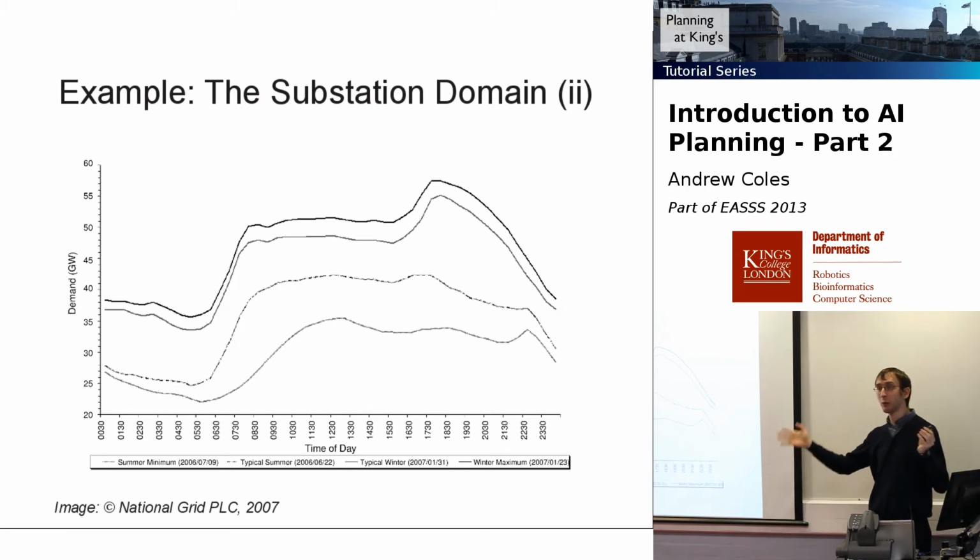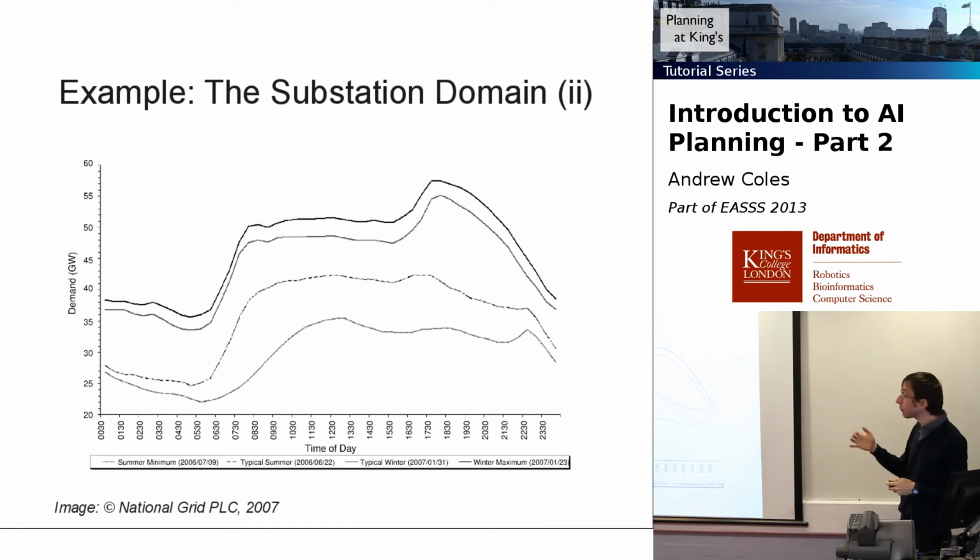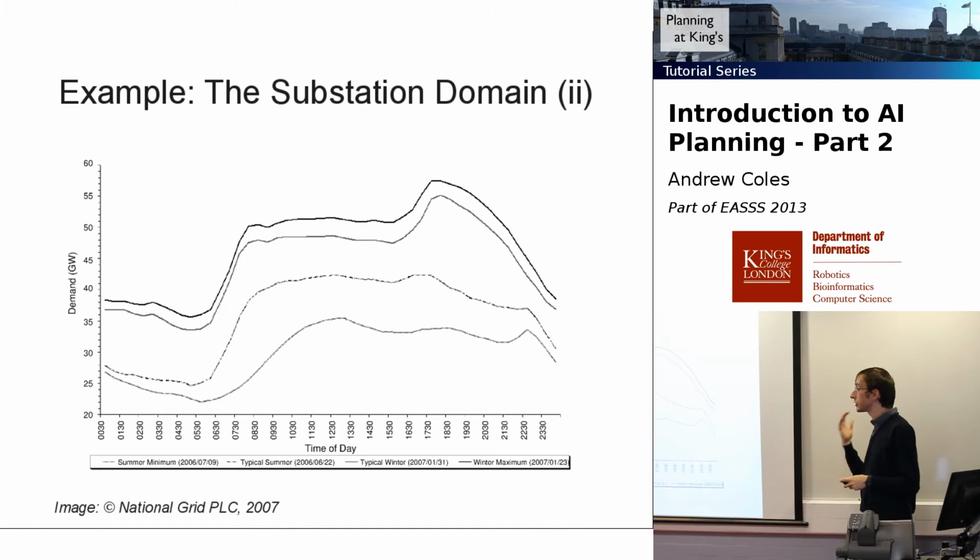And they take power in from the line on the upswing of the sine curve with AC, and then they release it on the downswing. And the net effect is roughly, you could say, if we're going to switch in a capacitor bank, it will increase the circuit voltage by 0.02 per unit volt, so about 2%. It's a ballpark figure. And then the other piece of equipment are transformers.